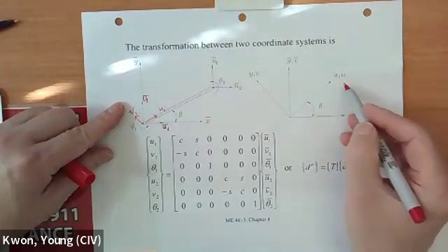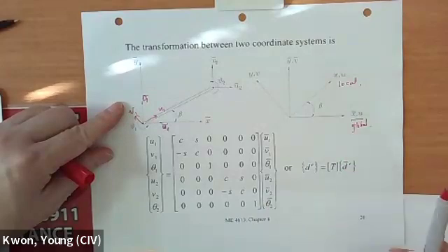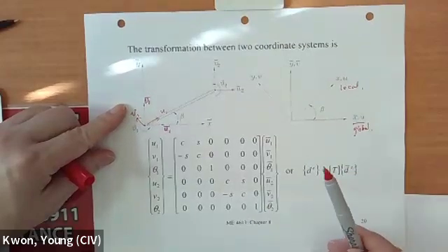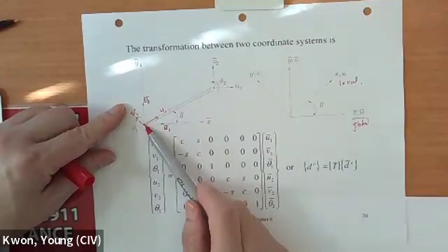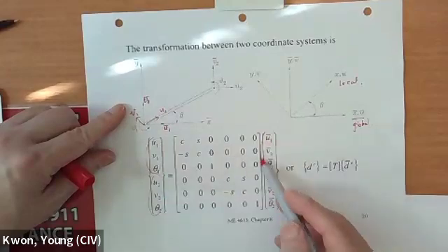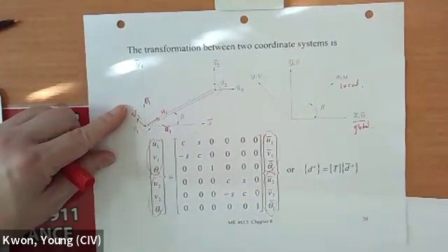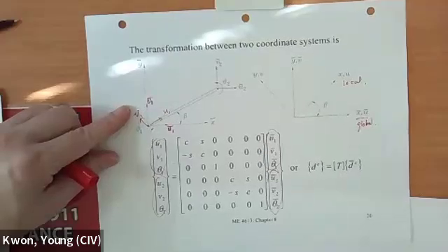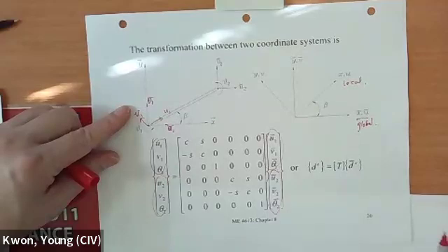And this is local. Okay, like a truss structure. But I have 6 degrees of freedom because I have 3 degrees of freedom per node. Right? Previously, we had 4 degrees of freedom in a truss structure. But this is 6 degrees of freedom because you have also slope here.